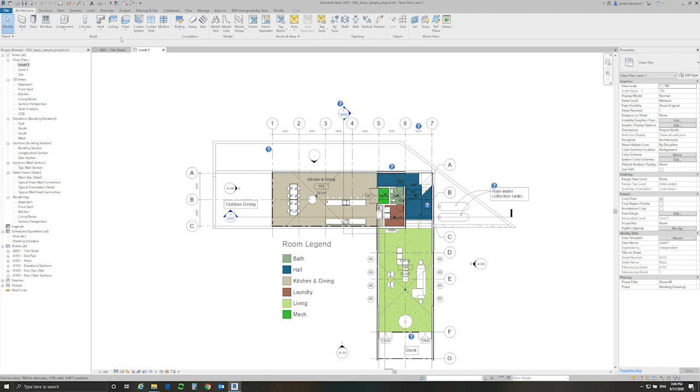So when I'm trying to tell you guys how to create a wall, for instance, I would say, go to the Architectural tab, in the Build panel, and select the Wall button. And you could navigate to that because you see the Architectural tab, the Build panel, and then the Wall button. And that's how I'm going to inform you guys on what button we're using to create a certain element. So just so you know, you have ribbon tabs, then you have panels, and then ultimately commands, and you can have drop-downs and commands for different variants of a certain command.